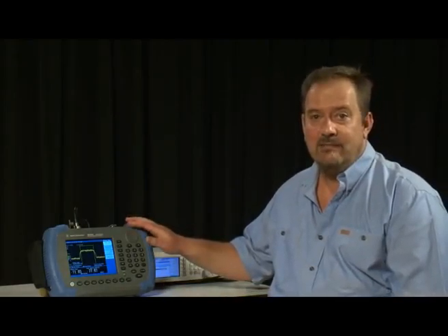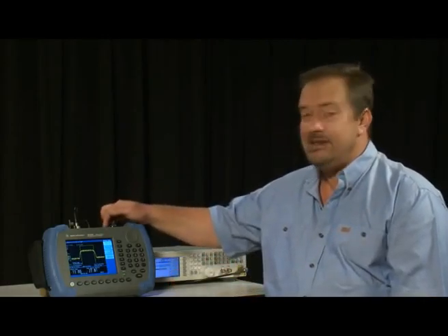When out in the field, we don't want to have to set up each measurement from scratch every time. So let's see how we can use the N9344C's save and recall capability to save and recall instrument states, and also how to save a screen capture of the measurement results for including in a report, for example. Here I'm going to be saving files to the analyzer's internal memory, but be aware you can just as easily save and copy files to and from a standard USB memory stick that you insert into the top of the instrument.